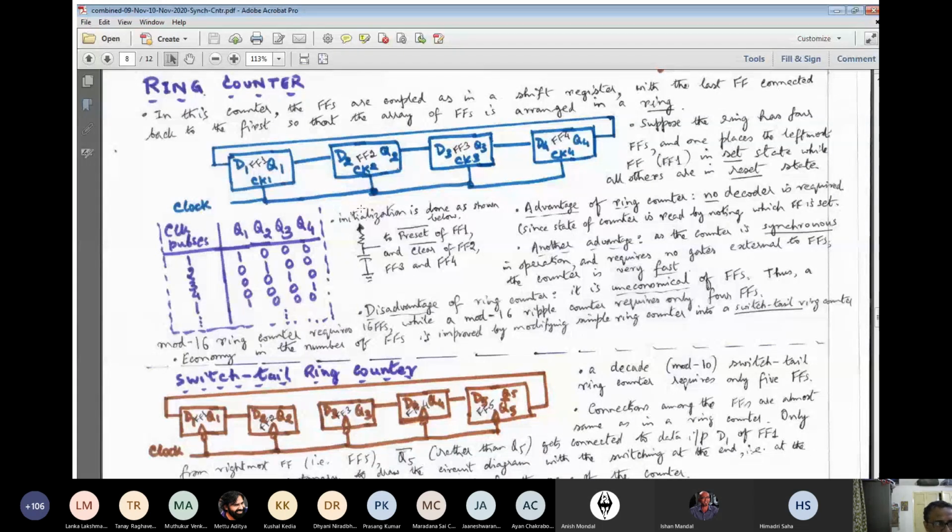Say we choose C to be a value of 0.1 microfarad and R to be some kilo-ohms, 3.3 or 4.7, whatever. Based on that, you can find some microseconds of clock period. The RC time constant should be much lower than the time period of the clock, because its effect should last only for a much shorter time than the clock period.